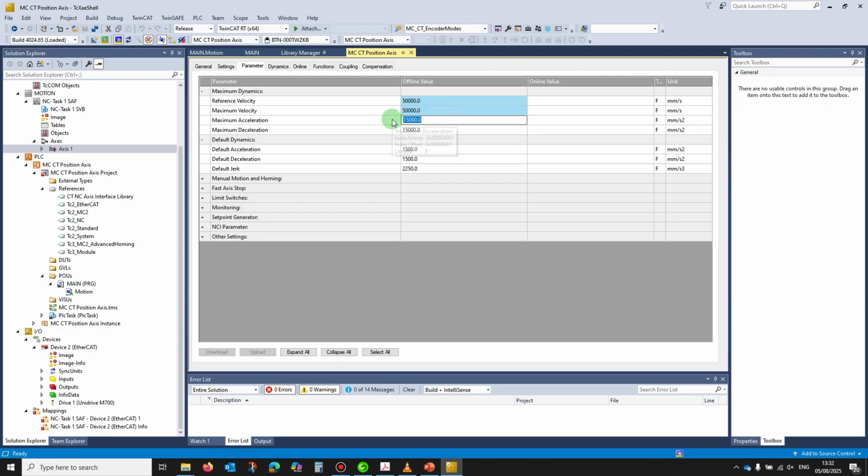And then I'm going to take the maximum acceleration limit and put it out of the way. So I'm going to go 1e plus 20, which is a shorthand way of saying 1 plus 20 zeros. Put that in and do the same there. So those acceleration limits won't cause us problems when we're messing about with the inputs and outputs. Last of all, I'm going to go and set the jerk also to that number for a different reason. It's just so that if you put in 0 as your jerk, you'll actually end up with a linear profile, because you'll reach your maximum acceleration within one sample.